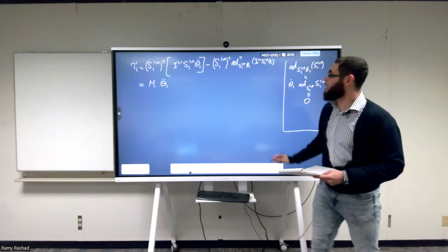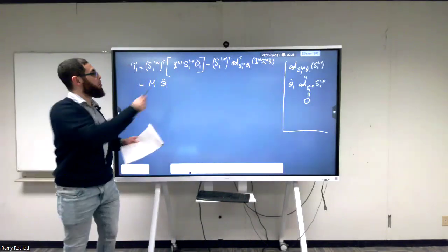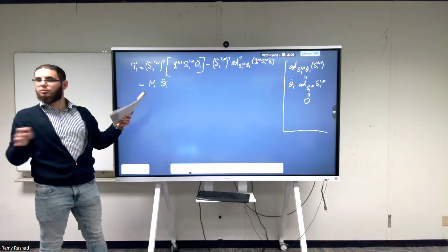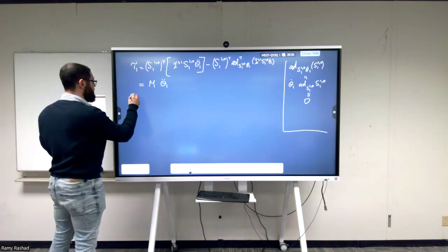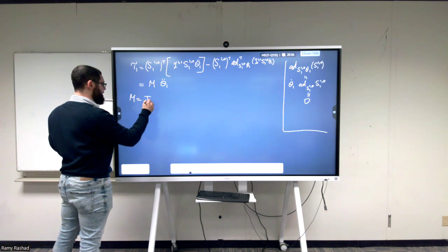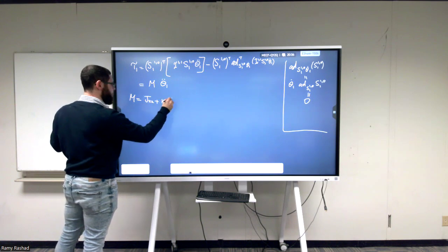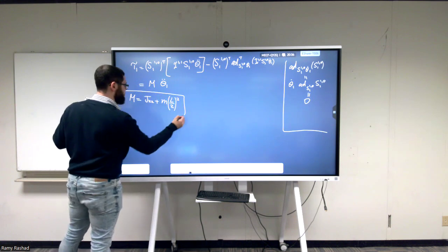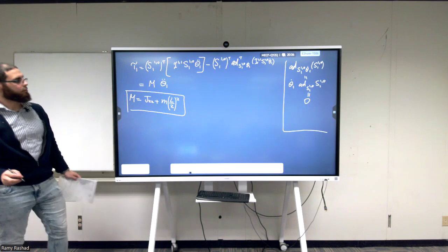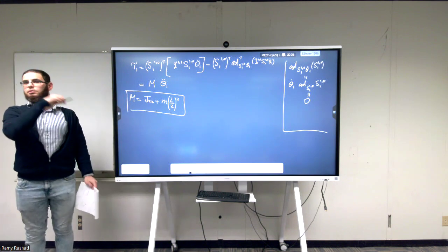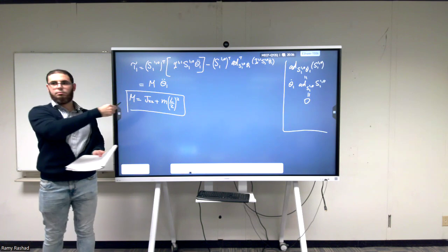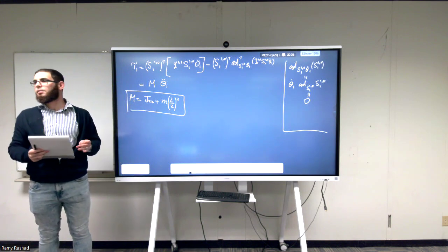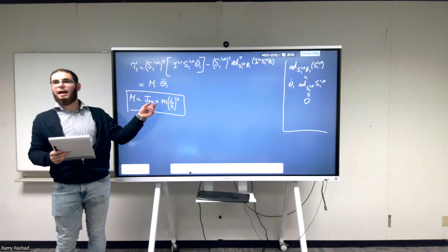Now, what I'm saying is that multiply this S transpose by the inertia tensor by the S. In the end, you're going to get this M. This is your homework to try out for yourself. The M will be equal to JZZ plus ML over 2 squared. What is this expression telling us? Parallel axis theorem, exactly. This is nothing else than the parallel axis theorem, right?